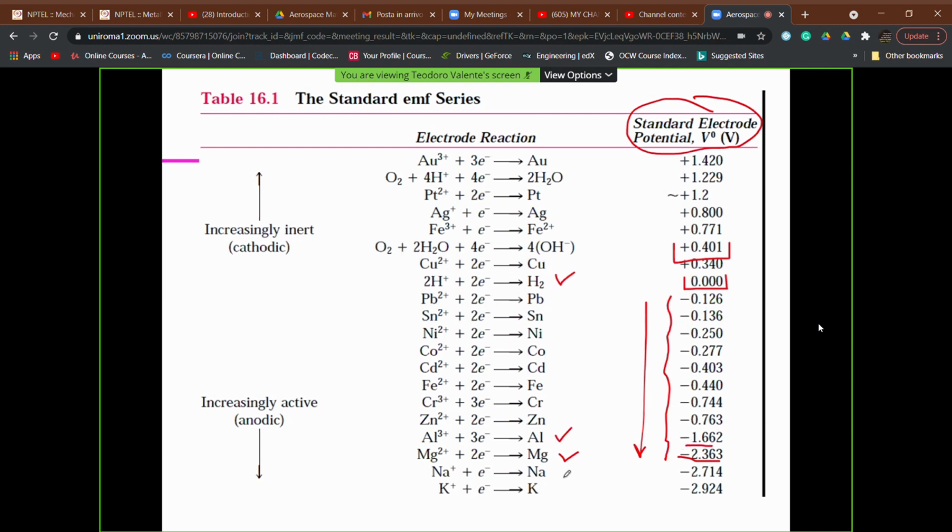And if you remember when we discussed some time ago about magnesium alloys, which are ultralight alloys due to the very low mass density of magnesium, lower than that of aluminium, we already said that these materials in some formulations are quite interesting for aerospace applications, not hot applications, the melting temperature of the materials being substantially comparable with that of aluminium, around 660 Celsius.